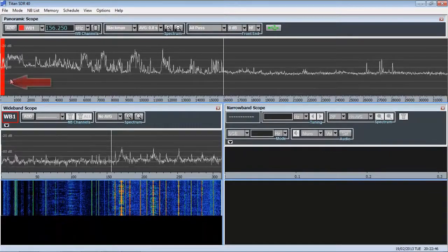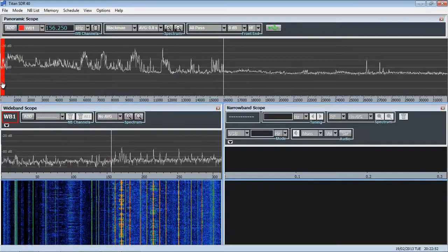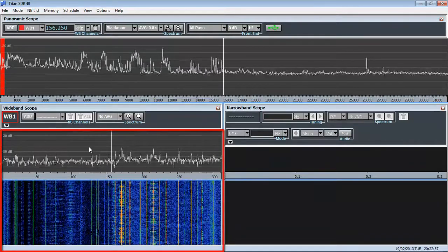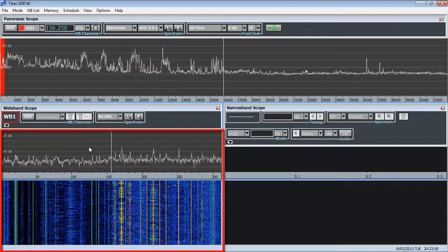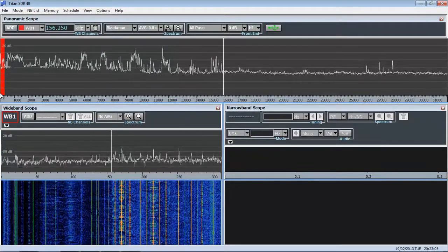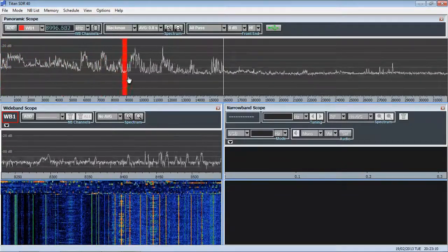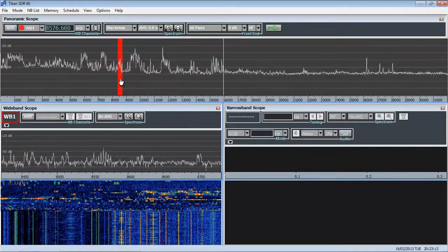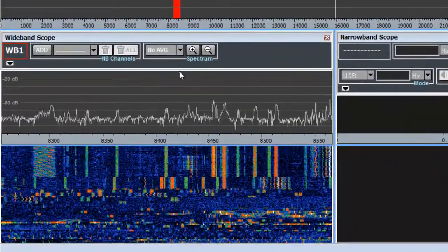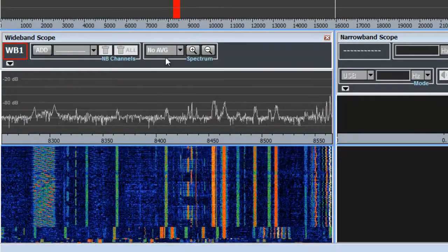The new wideband channel is allocated at the left of the displayed spectrum and is represented by a colored shaded area. The wideband channel spectrum and waterfall appear in the wideband spectrum scope. Tuning of the wideband channel is obtained by dragging its shaded area. While dragging, the wideband channel center frequency is modified accordingly in the frequency edit box. Also, the wideband spectrum scope allows to set the averaging time period and to perform zoom and dezoom operations.